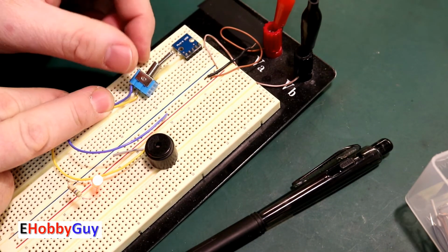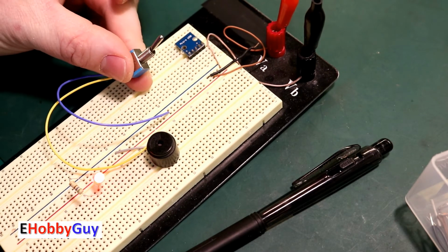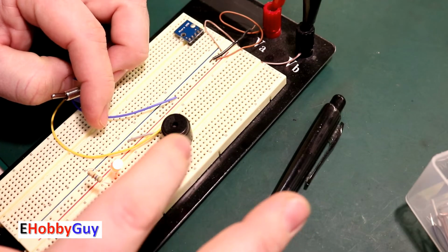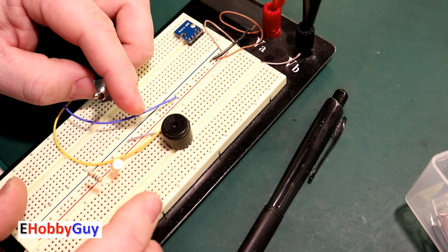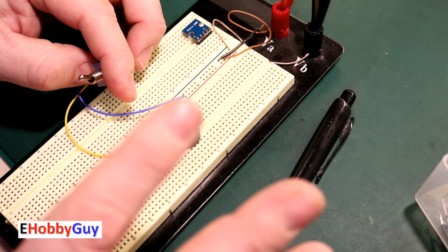Yes, that's exactly what happened. Here's the bypass switch. So the bypass switch works. The red LED is lit right here. Let's wire up a second set of these and make sure we can do the exact same thing. And we'll measure the current draw at that time of the entire circuit at 12 volts.